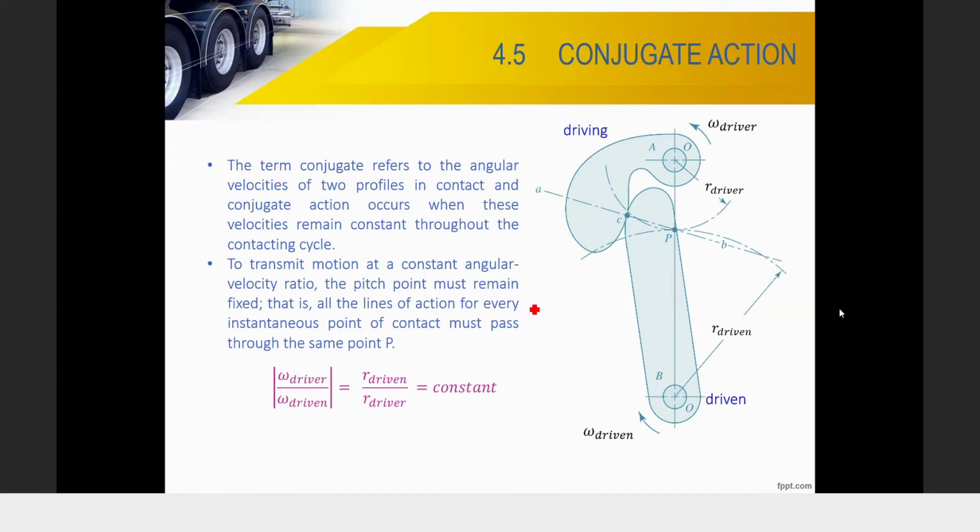For example, your drive gear is 1200 RPM from the motor. But you want your output shaft, the driven gear on the second shaft where you have the gear mounted, to be slower. So the diameter of that gear has to be half of your driver gear. So it means you reduce it by, sorry guys, I said it backwards. It means your drive gear is small, the diameter of your drive gear is small, but the driven gear must be bigger, 2 times the diameter of your drive gear. So that comes into the speed ratio, driven and driver.